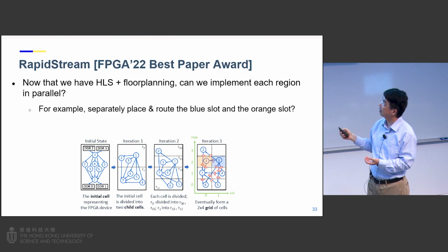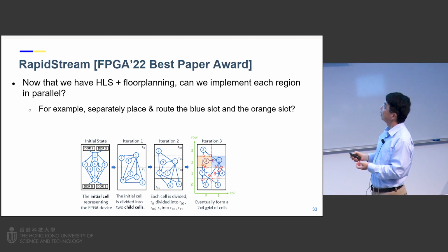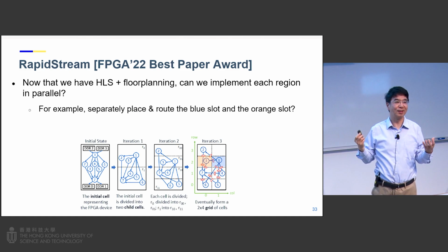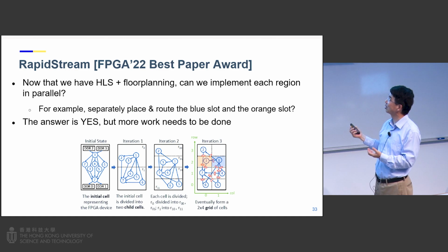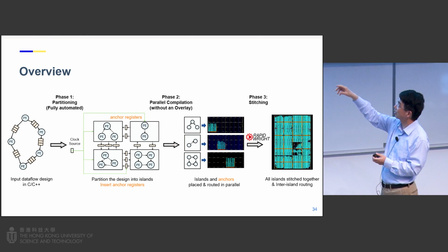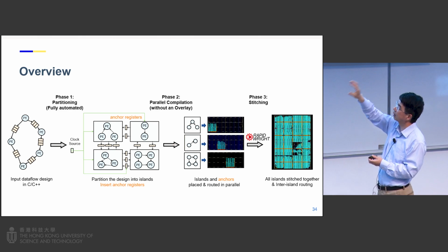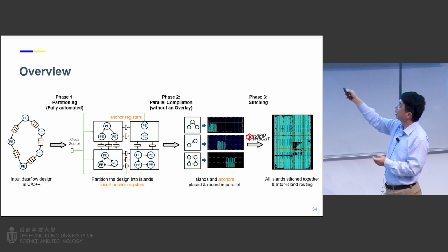So we have that, and we separate the place and route into slots. Now we're in business. We can optimize each slot independently, right? So it was never possible. This is by considering space and time together. So this is actually the circuit. You start with a data flow diagram that has multiple PEs that communicate through FIFOs.